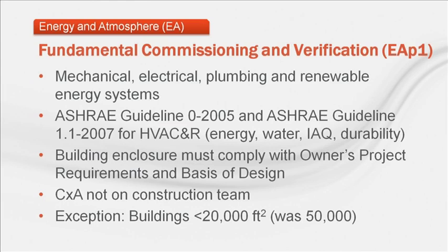For the prerequisite, once the building is more than 20,000 square feet, it's required that the commissioning agent not be part of the construction team. He or she can still be part of the construction firm for the prerequisite. The basis for energy and the minimum requirement threshold have both changed from the 2007 version of 90.1 to the 2010 version. We covered 90.1 in an ENL, but I'll touch on a few high-level changes today.